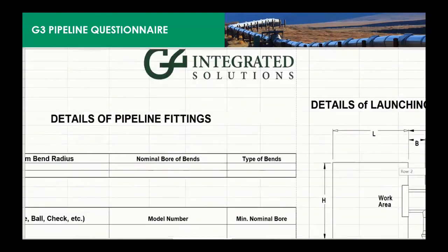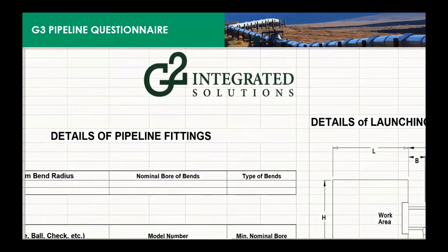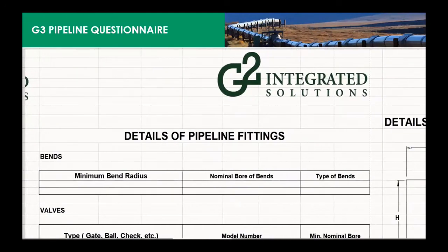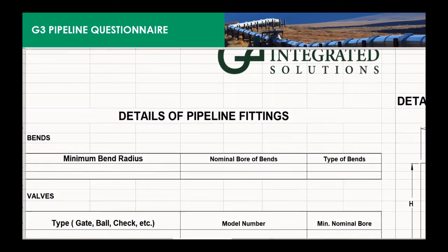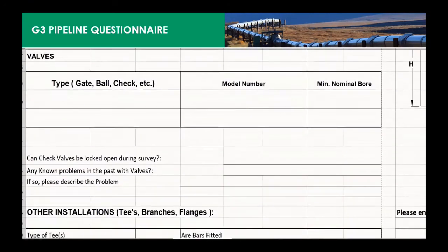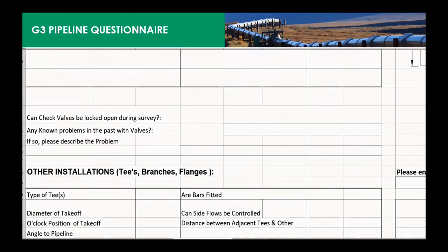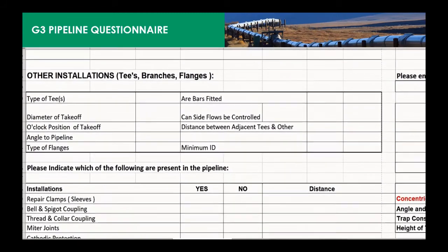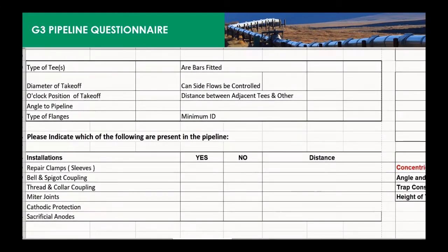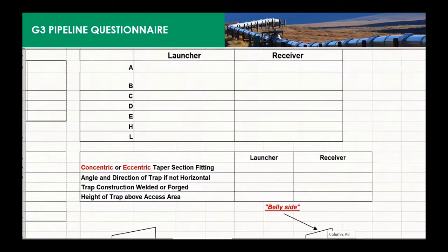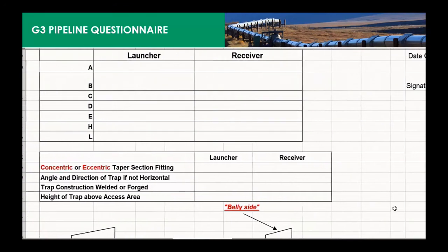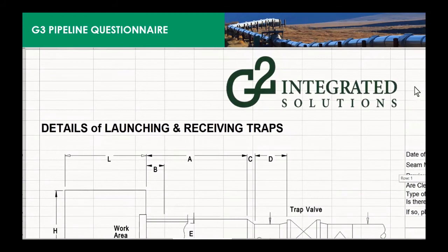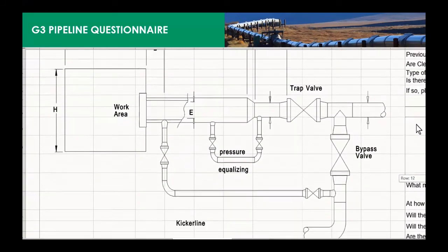Smaller diameter lines with heavy wall thickness are a very big problem for MFL tools because you have to magnetize these ones with very small tools. But you have to provide the amount of magnetic field necessary to saturate the steel in those heavy walls. Of course, you will also need more differential pressure in order to be able to move this heavy tool with the small diameter section.